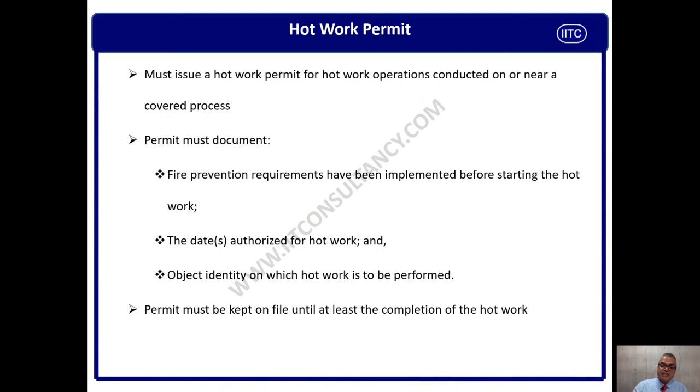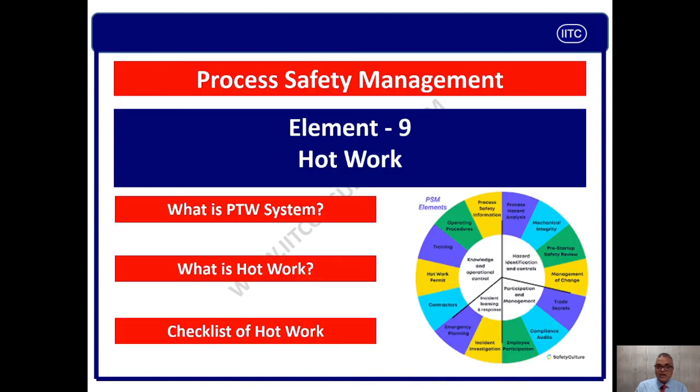So guys, these are very important elements. Now I hope you will be able to answer the following questions: what is the permit to work system, what is hot work, and what are the checklists?